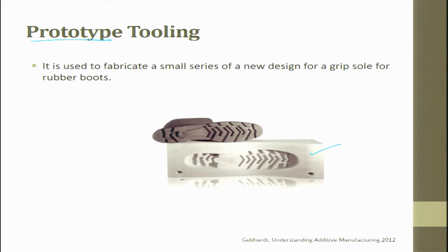You should also understand that making tools or dies for mass production is expensive. So, only for that we talk about the concept of prototyping of tools. Here the tool is made as a prototype, and after this the corrections will be made and the final design will be accepted, and directly this tool will be produced. That is called rapid tooling.